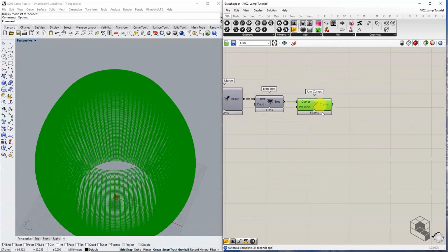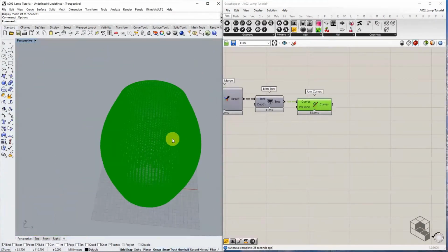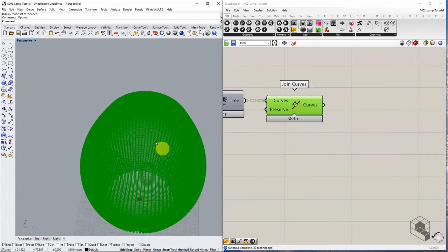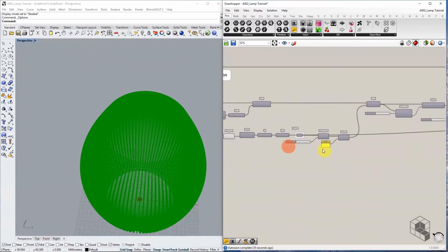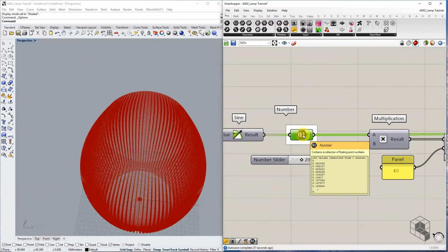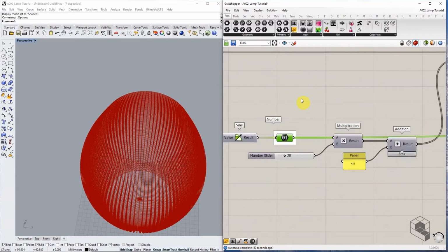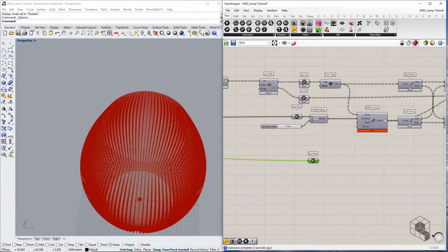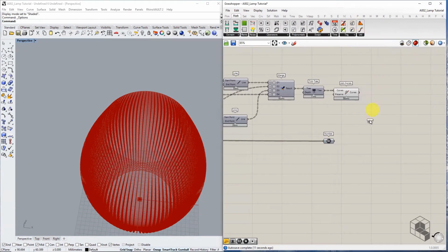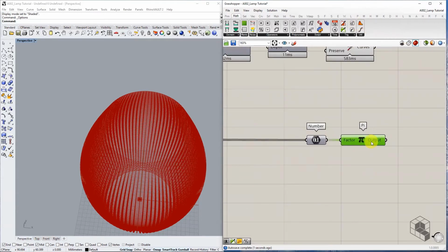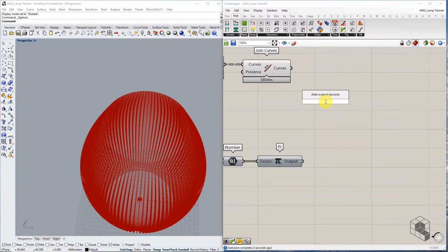The last step that we need to do before lofting these 150 curves is to rotate them. Now for rotating these curves, we will again use the number series that we highlighted, and we will be multiplying this with the number pi. So we go to the number component, bring it all the way to the front, and bring in pi. You also bring in the rotate command.